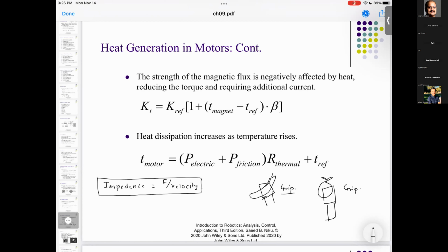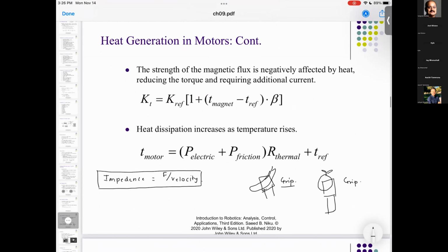So what this means is this robot is interacting with the task or with this object in terms of the force that is being applied and the rate at which the force is being applied. So the important part here is we need to match the impedance of the soft object and the impedance of the hard object for that successful operation. I'll give you another example.